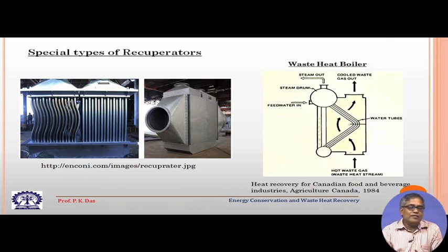With that, let us go to special types of recuperator. Now, if we see heat exchangers, there are different ways of classifying heat exchangers. One way is that we can classify the heat exchanger as recuperators and regenerators. Recuperators means continuously there will be heat exchange between the cold fluid and the hot fluid without having any intermediate storage medium.